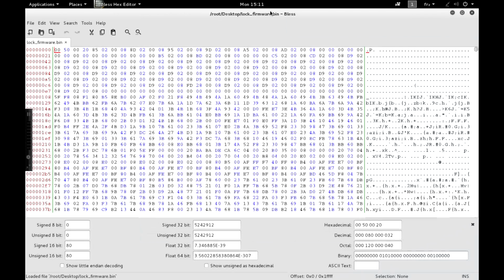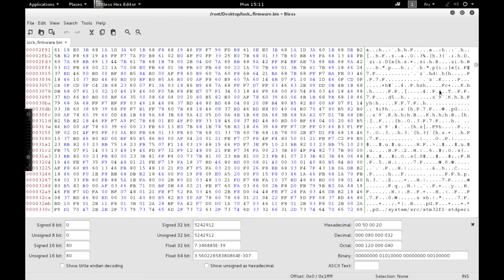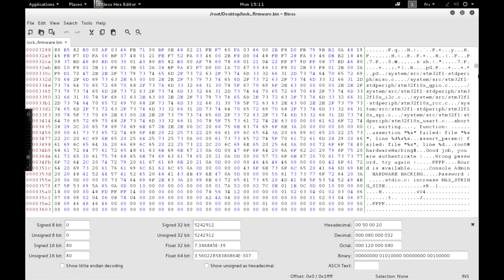Okay, here we have the electronic lock firmware, of course without readout protection for the expert. If you read the content with readout protection, you read only 0 or FF, depending on the microcontroller. So most of the time, you can read the firmware like that.